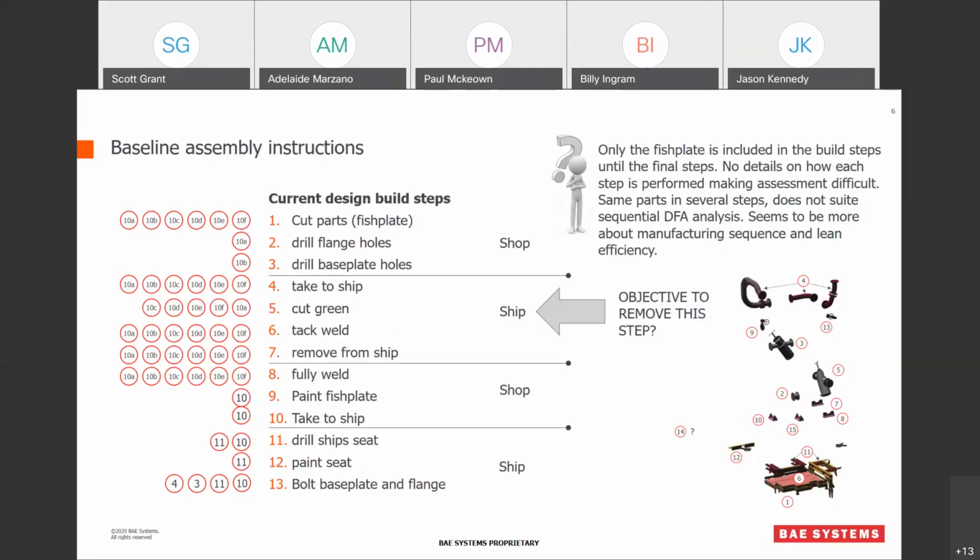I think another important piece of information is what is not manufactured in the company but comes from outsourcing. It needs to be assessed separately. So you need to understand how the other parts come together, if they come as a single component or as a sub-assembly already. Because if they come as a sub-assembly already, then there might be an error in there, and then you will not be able to identify it, although you might have done correctly all the fish plates and all the things in-house.